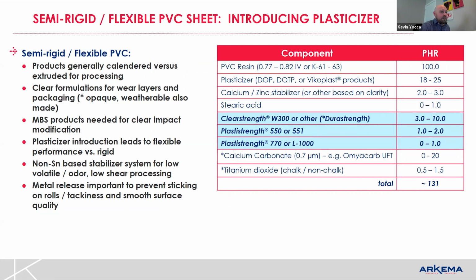I think the most common thing I see after that, again, this is not me being an acrylic guy, but probably would be acrylics, because the thing you could use with an acrylic is you could decide the functionality. Do you want it to be a lubricating process aid that gives you metal release and a little bit of fusion control? Do you want it to be something that's a mid-molecular weight process aid that can give you melt strength and you can tune the use level for gelation purposes?